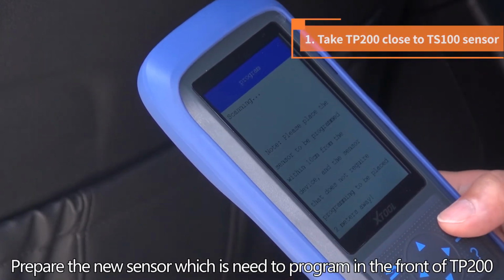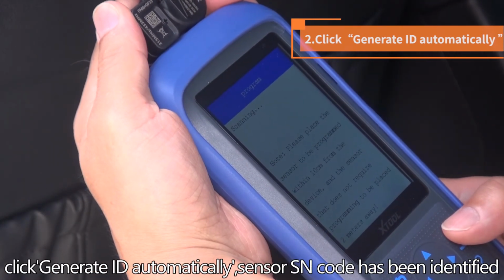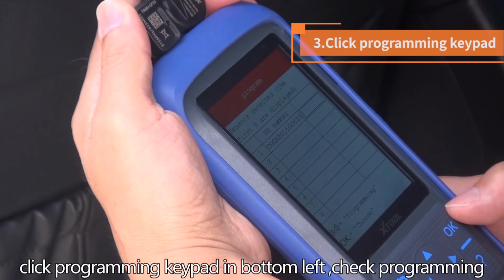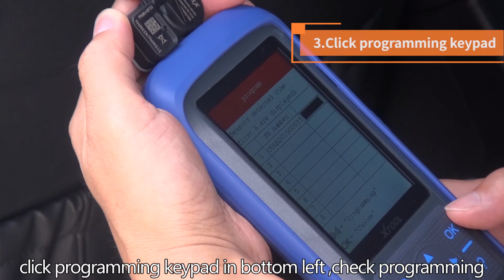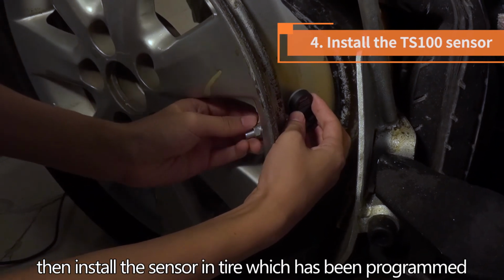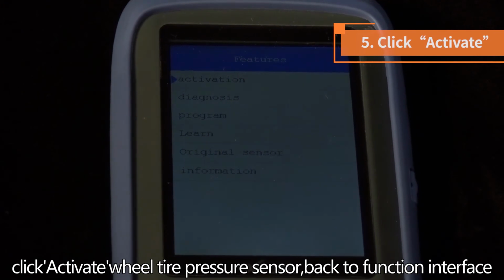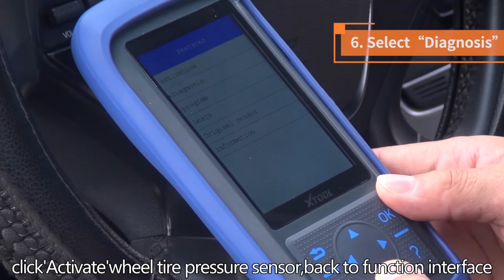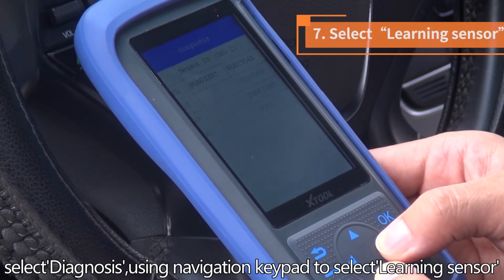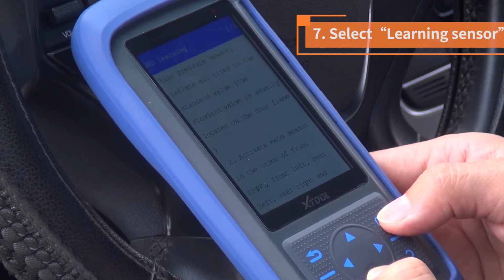Prepare the new sensor which needs to be programmed in front of the TP200. Click Generate ID automatically. The sensor SN code has been identified. Click the Programming keypad in the bottom left. Check Programming. Then install the sensor in the tire which has been programmed. Click Activate Wheel Tire Pressure Sensor. Back to the function interface, select Diagnosis, using the navigation keypad select Learning Sensor, and view the hint to learn the sensor.